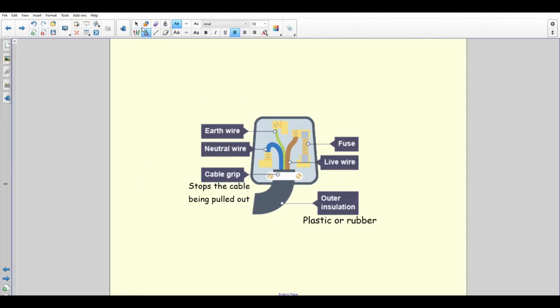Right, let's go through the wires now then. So we'll start with the live wire. So this is at 230 volts. Now I'm not going to write these things because you can see them on the picture, but it is brown. Bit silly, but the way I remember this is a live wire is brown because that's what colour it makes your trousers go if you touch it, because it's very dangerous. Take from that what you will. So live wire, touch it, it's going to hurt you because it's at 230 volts. You are at 0 volts because you stood on the floor. That's a potential difference of 230 volts, which is enough to send electrons through your heart and cause some damage.